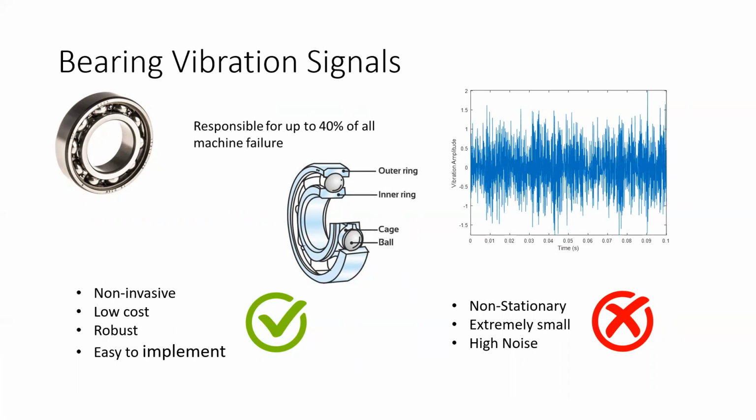Vibration analysis was found to be the most favorable approach due to the non-invasive, non-destructive nature of acquiring online data samples. Signals are recorded using accelerometers mounted to the machines and can be used to gather data without the need to disassemble or power down operating equipment. The challenge with using these signals is that they are non-stationary, extremely small in amplitude, and susceptible to high levels of noise from the environment.